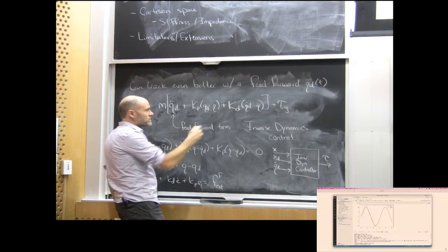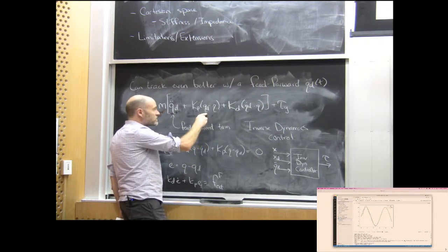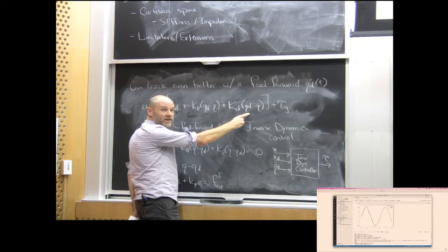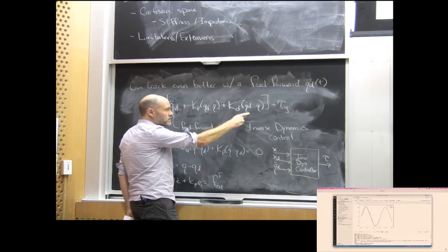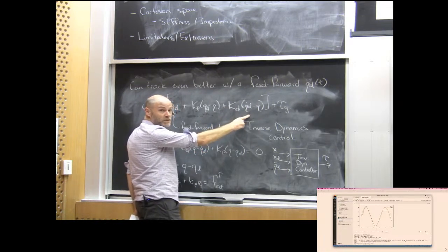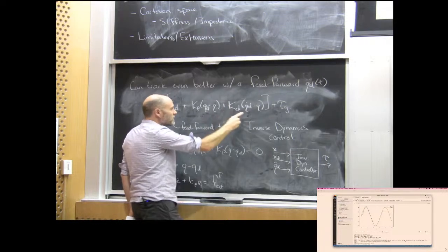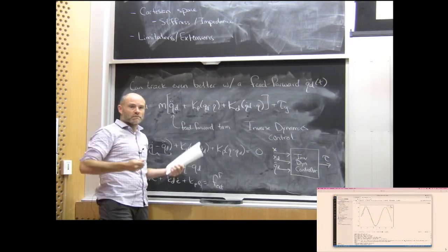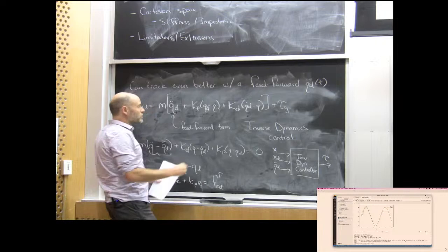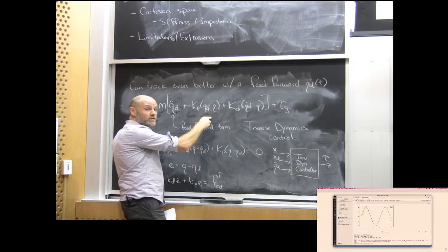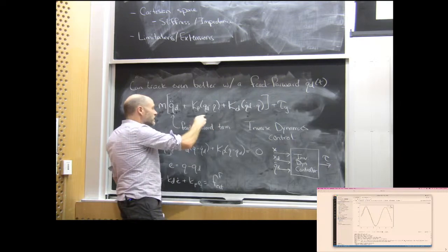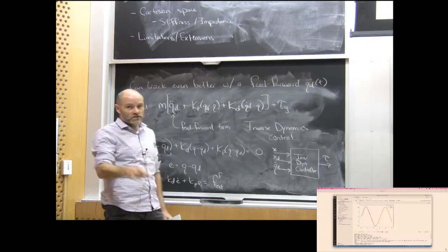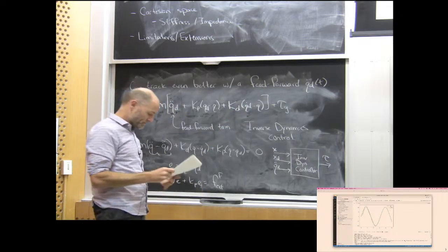EWA allows you to send Q desired, but it doesn't actually allow you to independently send Q desired and Q desired dot. I believe they made a safety argument with that: if you could imagine a bad user sending inconsistent Q desired and Q desired dot, that might break their safety proof. So they instead take a sequence of Q desired, add a little bit more delay even, take finite differences to estimate Q dot, and then send that as a command. But you're only actually allowed to talk to the robot with Q desired over time.